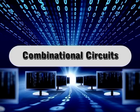Now comes one of the most important topics, called combinational circuits. We have actually two types of logic circuits, sequential and combinational logic circuits. Sequential logic circuits are those whose outputs are dependent on both their present inputs and their previous output state, giving them some form of memory. The outputs of combinational logic circuits are only determined by the logical function of their current input state, logic 0 or logic 1, at any given instant of time.